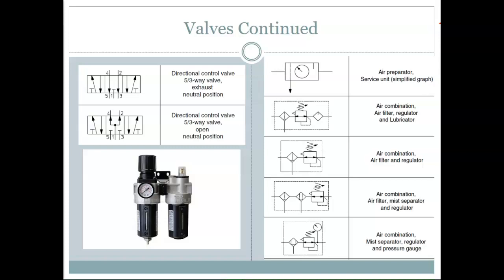But it also is, when you compress air, you tend to push out all the water. The problem with that is in your compressor tank, you have to drain it periodically. If you don't, you can get quite a bit of water in there. Water in a metal tank. Anybody think that's a bad idea?